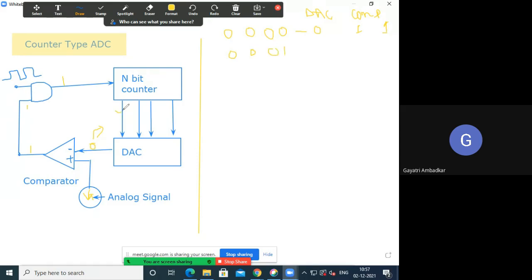याचा आउटपुट काय झाला आता 0 0 0 1. So this 0 0 0 1 will go to DAC. हा digital data DAC ला गेला, right? DAC what it will do? It will convert it into analog. So equivalent of 0 0 0 1, let's say it is 1 volt. Analog किती होणार? 1 चा analog 1. Okay. आपण पाहिलं की DAC कसा आउटपुट करतो एनालॉगला. सो 1 बीट झाली तर हा 1 व्होल्ट देईल. सो हिअर नाव आउटपुट will become 1. Analog आहे 1 volt. This 1 volt is analog. Okay. So DAC output will be 1.